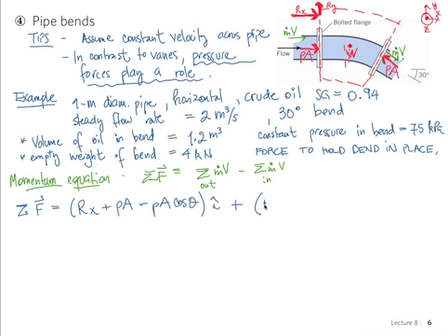In the y direction we have Ry. The pressure on this side doesn't have any component, but the pressure on the other side does, and it's in the positive y direction. So P A sine theta, and all of this times my unit vector J. And finally we have a reaction in the z direction which I've not drawn but has to be equal and opposite the weight because this whole thing is in balance. So this is our vector force. Make sense? Answer your question?